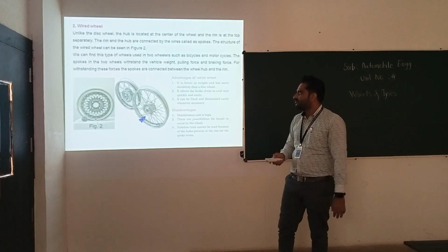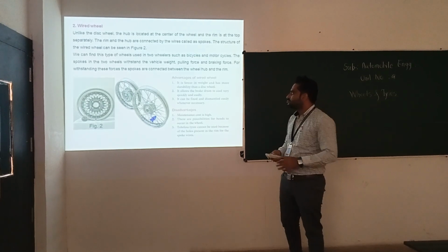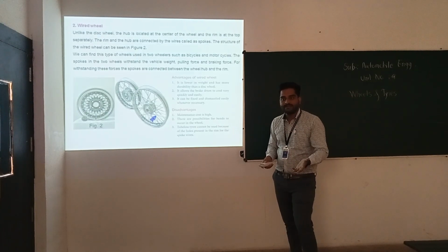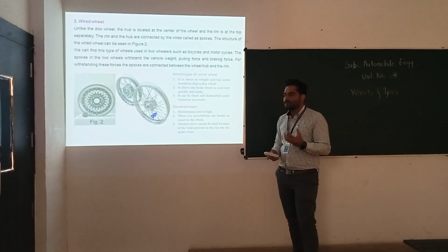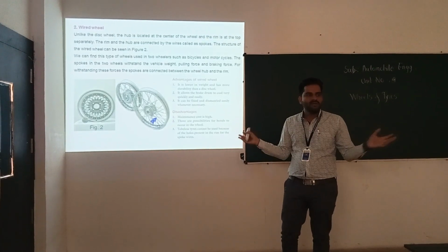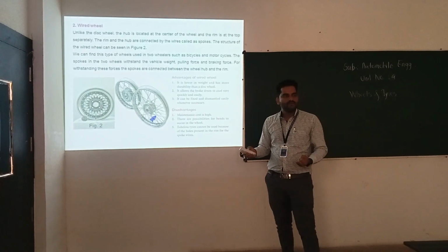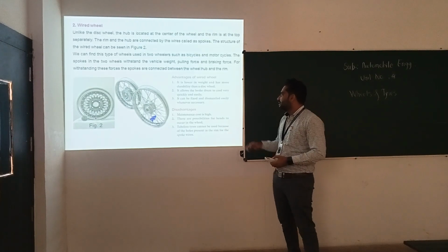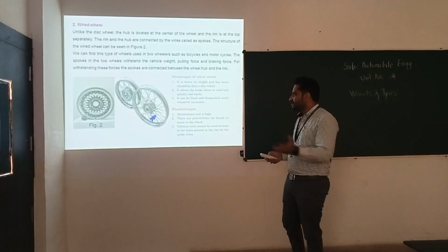Advantages of wired wheels. It is lower in weight but has lower durability as compared to disc wheels. It allows the brake drum to cool very quickly, because air passes very widely and quickly through these spokes and the wheel. So it will allow very quick cooling. It can be fixed and dismantled easily whenever necessary.